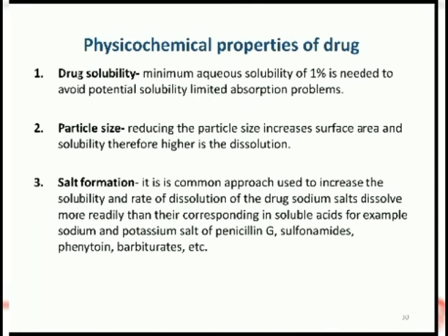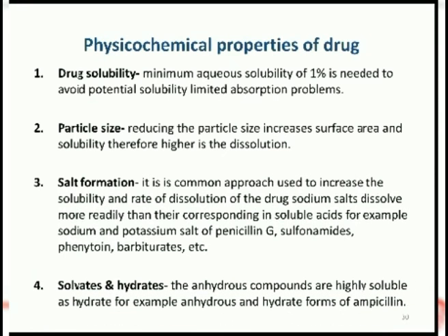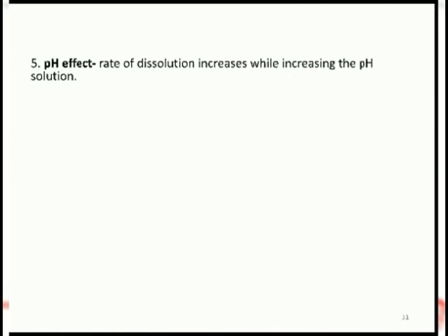The USP basket type apparatus 1 consists of a 40 mesh stainless steel basket attached to the end of the stirring shaft, which in turn is attached to a variable speed motor. A tablet or capsule is placed within the basket and immersed in the dissolution fluid contained in a round bottomed container and rotated at a speed specified.